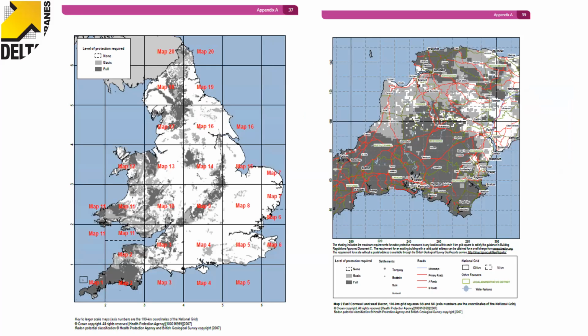So there are UK radon maps in there which show the risk due to radon contamination, basically, and on the kind of rock, you know, and the decomposition of the radioactive element, which is what radon is, the alpha particles. So if it was in Cornwall, then I'd be factoring in radon protection, because that's a high risk area and it specifies a level of protection for radon.